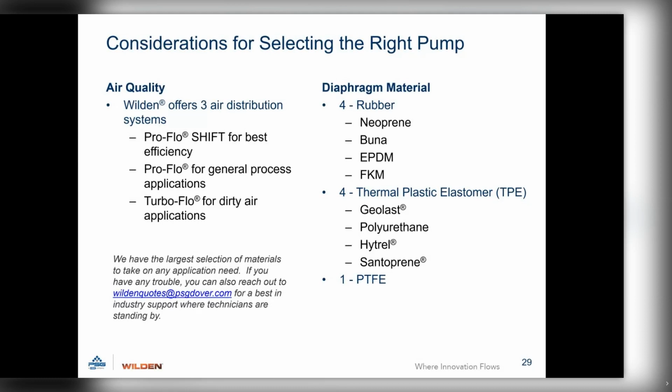When we get into our diaphragm materials, this is where the complexity starts, because we offer 9 different material options. Really only 3 styles though: rubber, thermoplastic elastomer, also known as TPE, or PTFE. And again, the material being pumped is going to dictate which diaphragm material you choose.